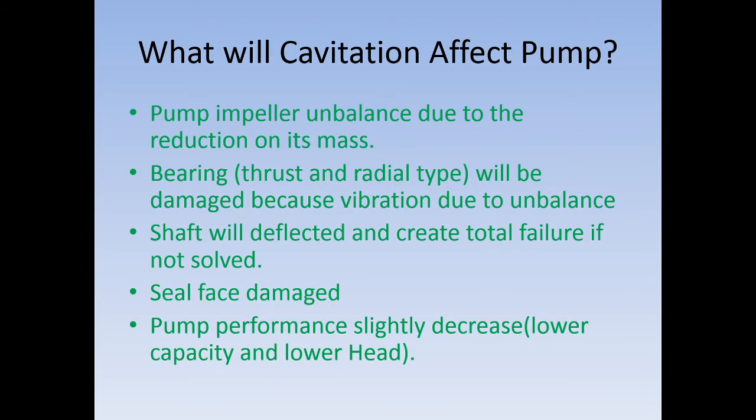What will cavitation do to pumps? As you can see here in the slide, the pump impeller is unbalanced, the bearing is damaged because of this vibration, the shaft is deflected, the seal face is damaged, and pump performance likely decreases, with lower capacity and lower head. In the test laboratory, usually the pressure goes up and down, up and down, and creates noise.